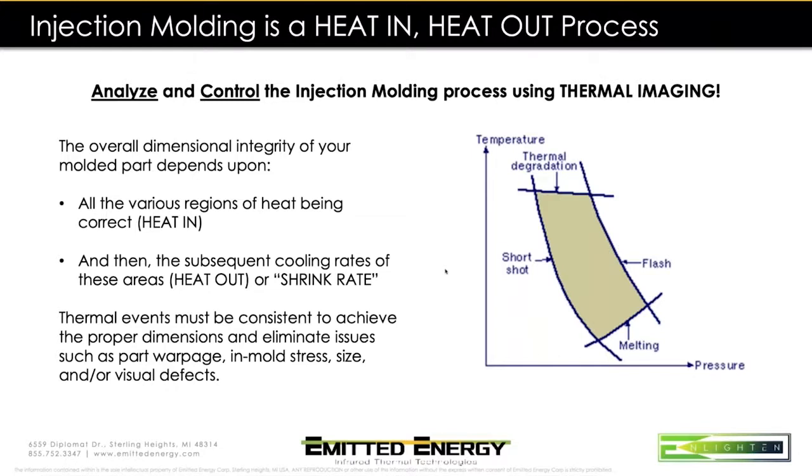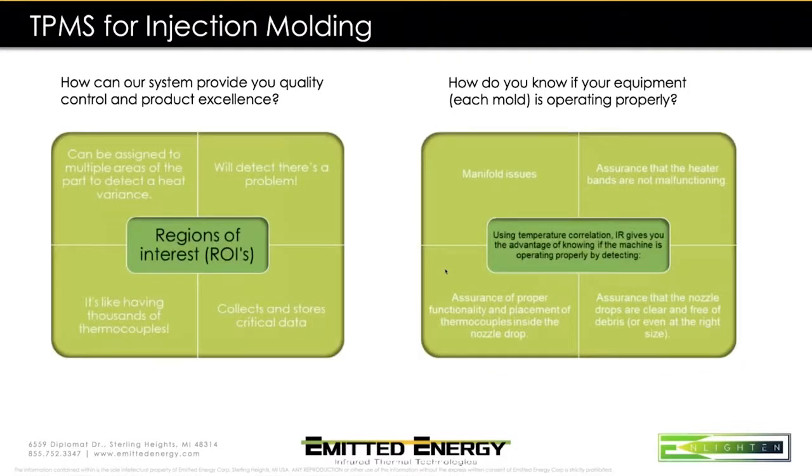And we'll be able to know through past data as we run thousands of your parts, and we'll be able to get the statistics of your part, what your 3 sigma should be, and be able to tell you with confidence that that is a good part, like it was last week, or like it was on first shift on first piece inspection. Or we'll be able to tell you something's changed and give you a direction there. Okay, that was a lot in a mouthful there, so I'll try to hit this one.